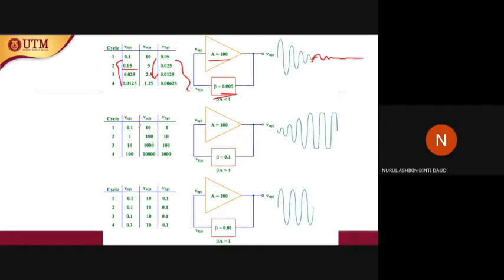All right. Next, when the beta gain is more than 1, what will happen? You can see that the output voltage is increasing, uniformly increasing. And it will saturate. At one point, the VUTP and VLTP will saturate the output, and later on your waveform will become like a square. You will not have a nice sine waveform if the beta gain is more than 1.